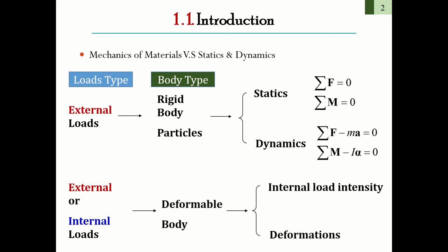It also has to equal the external bending moment, which equals the moment of inertia times alpha, the angular acceleration. That is from your dynamics course: F equals ma, and the summation of moments equals inertia times the angular acceleration.